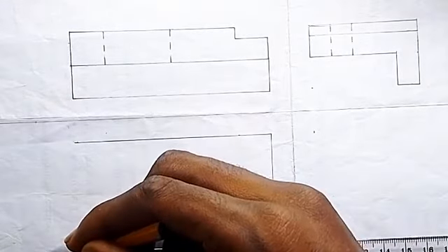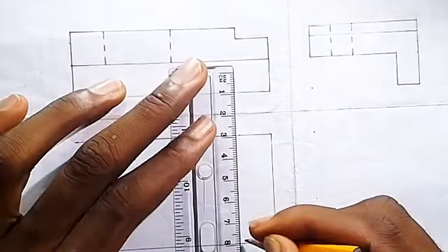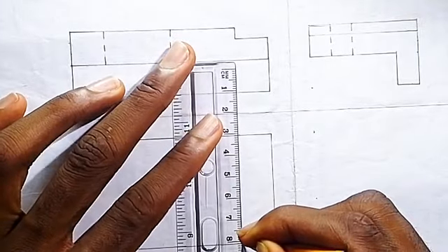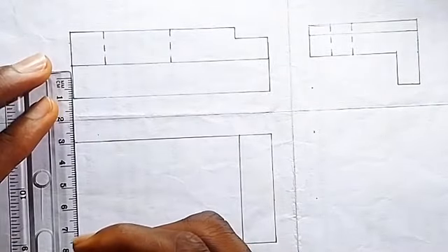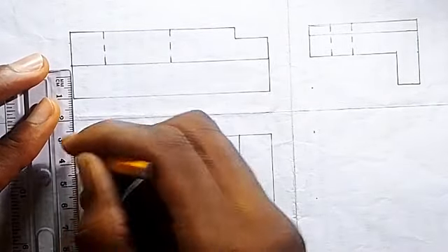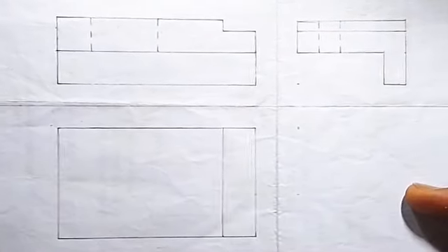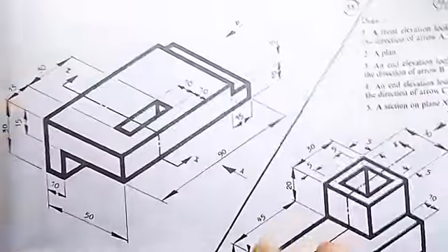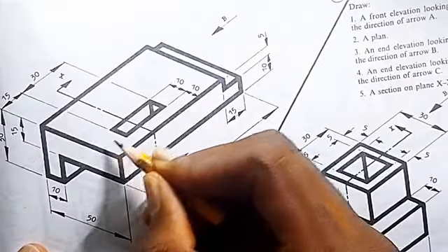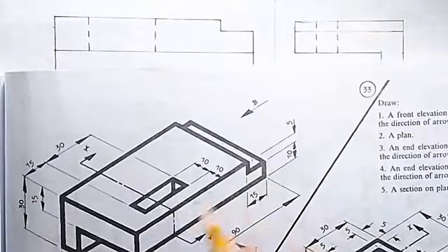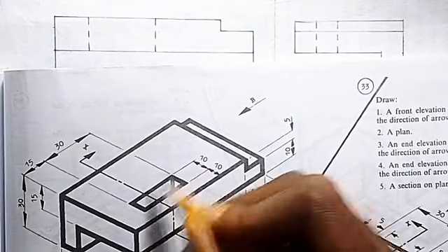Nine cm, then mark 1.5 here. So draw this other projection, which is this. Good. Then we join our block for the top. So the top is going to show us where the hole is, the hole that we do have. So where can we find the hole now? Remember, from this side we marked 1.5 from this part here. Then from this end elevation, which is this, mark 1 cm. So mark 1.5, 1 cm, then draw the hole of 3 cm.